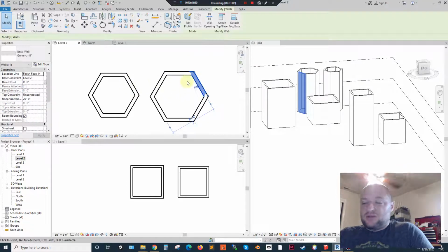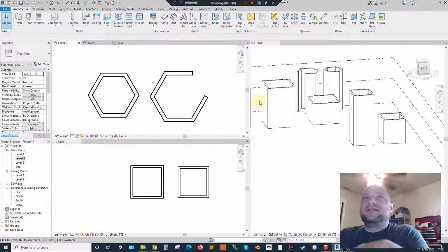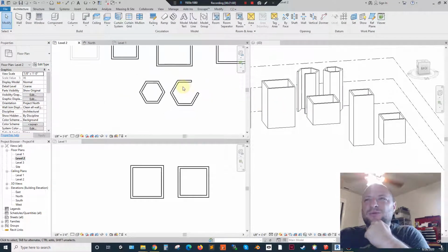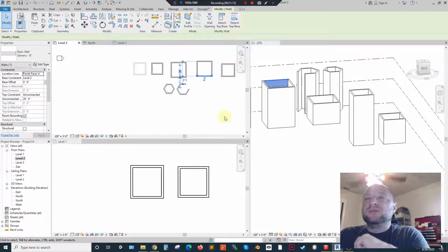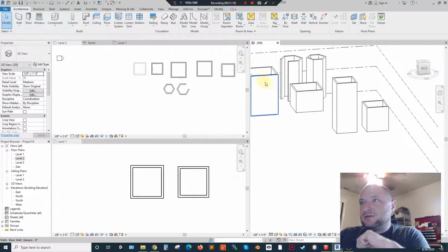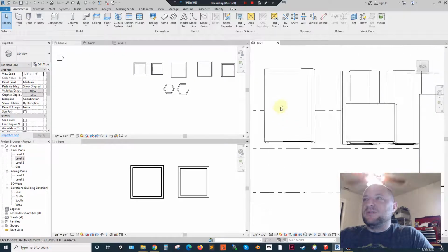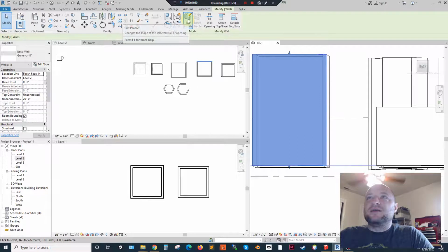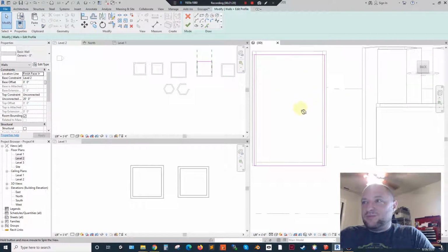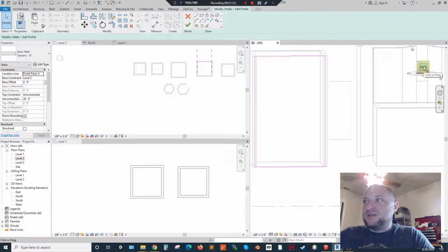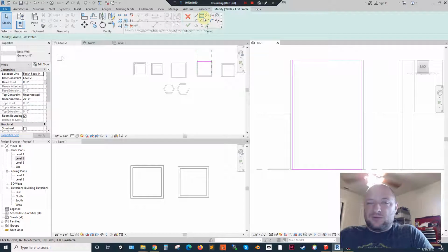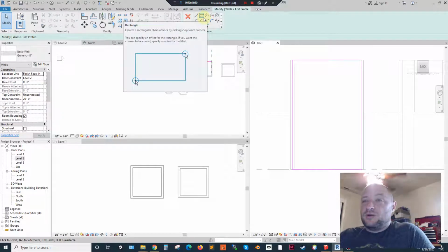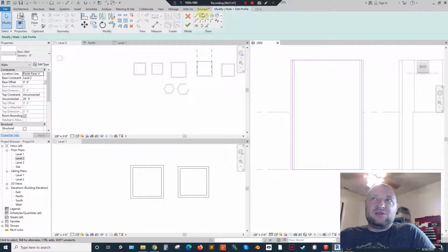Once you have a wall placed, you can actually go in and delete a chunk of wall. And then I'll cover it real quickly here, but we'll get into it a little bit more later as well, is actually being able to edit the profiles of walls. So if I go in here and I select, we'll stick with 3D view. So I've got this section of wall right here, and I can click on edit profile, and it's going to give me this kind of pink area here, and I can click on this navigation little widget right here in the 3D view to snap me to a particular view. And then it's going to give me these draw tools here, and we're going to get fully into editing profiles when we get into walls and floors and stuff. But for now, just realize that this menu is here and you can edit profiles.